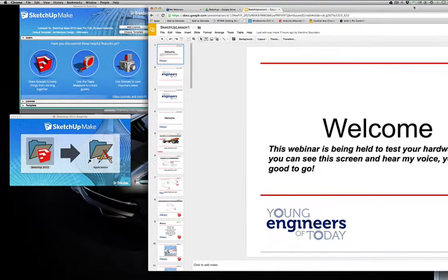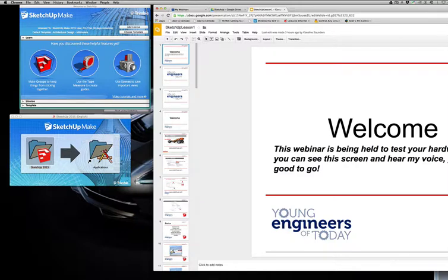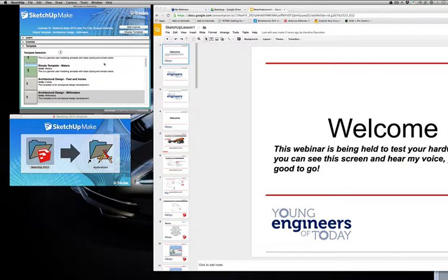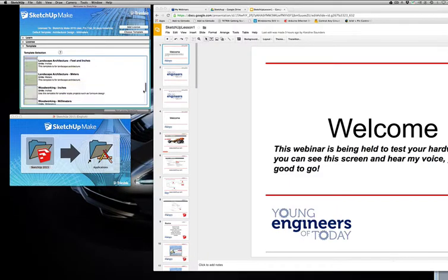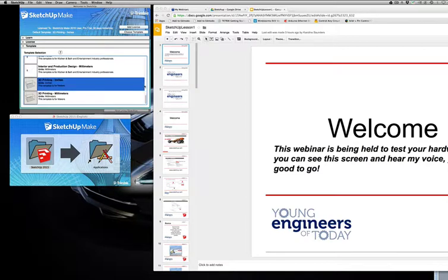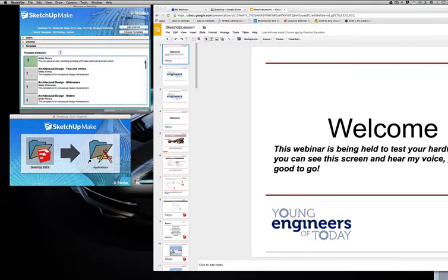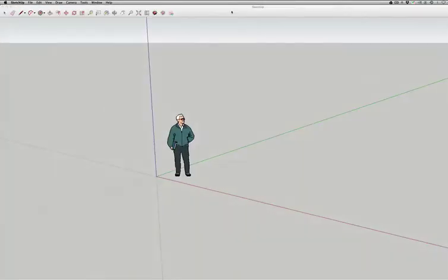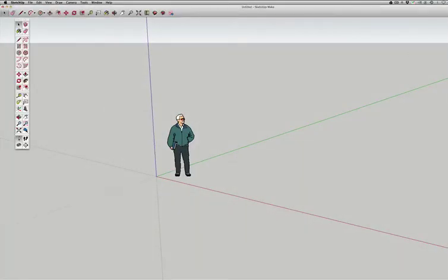When you go to install it, remember to drag your file right into the folders. You literally physically drag it into this. And then when you go to start it up, you've got to choose a template. Now, in the beginning, let's just do like we're doing architecture. There's architectural design in millimeters. It also has, which it didn't before, 3D printing in inches and millimeters. But we're going to go to architecture just to begin with, and then we'll start playing with the others down the road. Then once you have that, it's not obvious, hit Start SketchUp. And then it'll pop up. It should look like this.